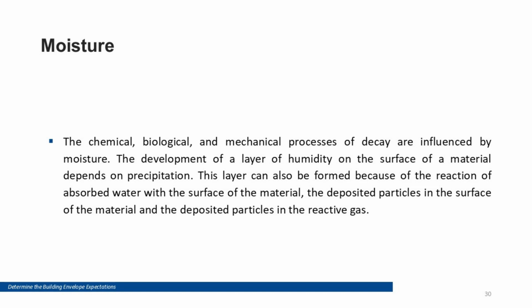Moisture. Moisture is a major driver of damage and performance loss. It can reduce insulation effectiveness, increase corrosion risk, and trigger mould. Good moisture management includes correct drainage and flashing, limiting humid air leakage into cavities, and using suitable moisture and vapour control layers so assemblies can dry safely.